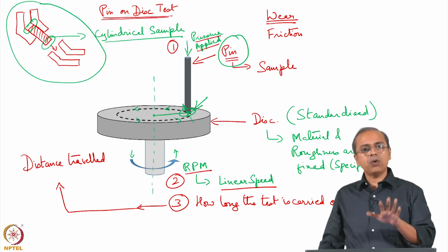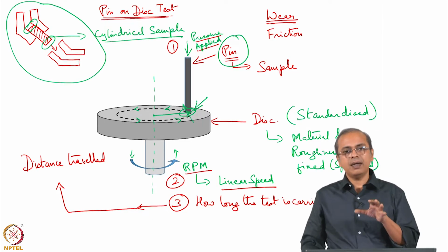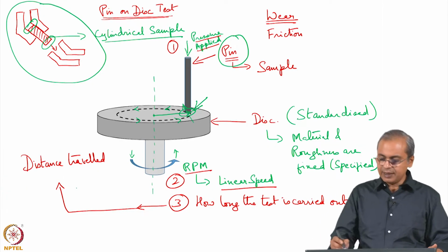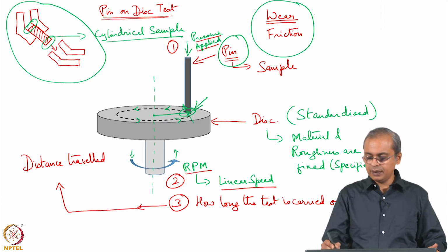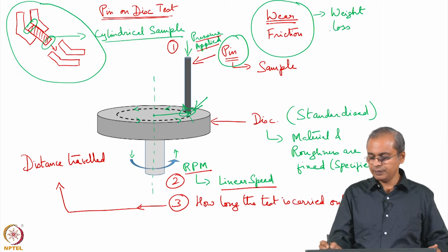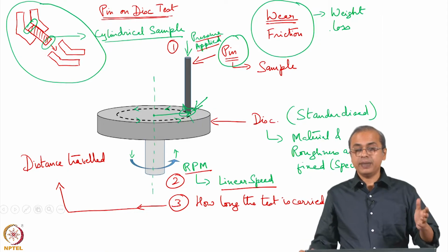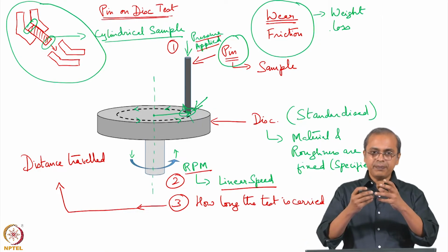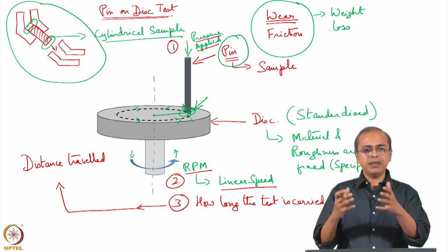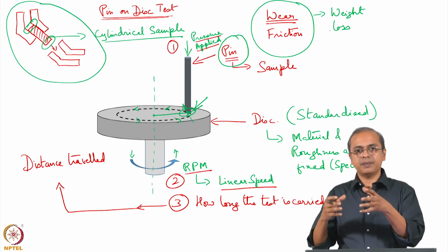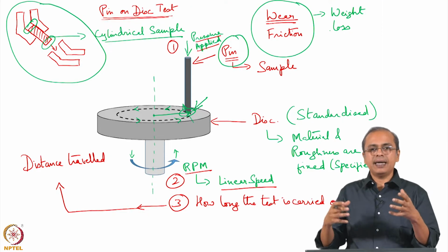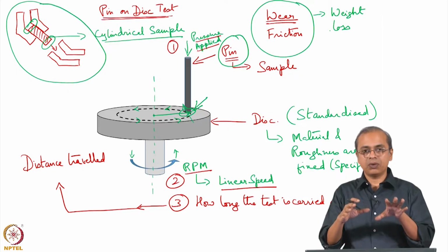And typically what are you comparing? The general aspect associated with wear is basically weight loss. So, essentially with friction, material slowly wears off, and then you are having less and less of that sample, and eventually in a technological circumstance, what this means is that at some point it will go below some tolerance value, and it may no longer be useful in that technological application.